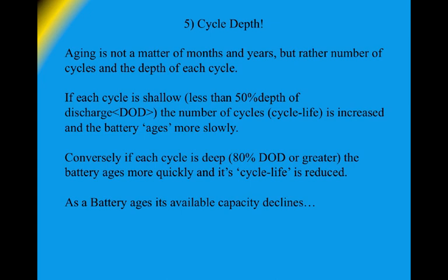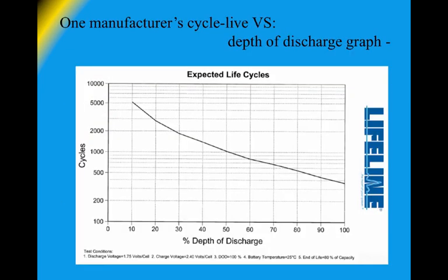This reduces the amount of backup charging we have to do on off-grid systems, and it also allows us as good a battery life as possible. But you noticed in the previous chart that less depth of discharge, like a 30 or 25% depth of discharge, as I mentioned, will extend the battery life even further. So, although there is a limit to it, generally speaking, we don't want to be going below 50% depth of discharge. And if we can stay in a 20 or 30% depth of discharge cycle, we're going to get many, many more cycles out of the battery and a longer life.